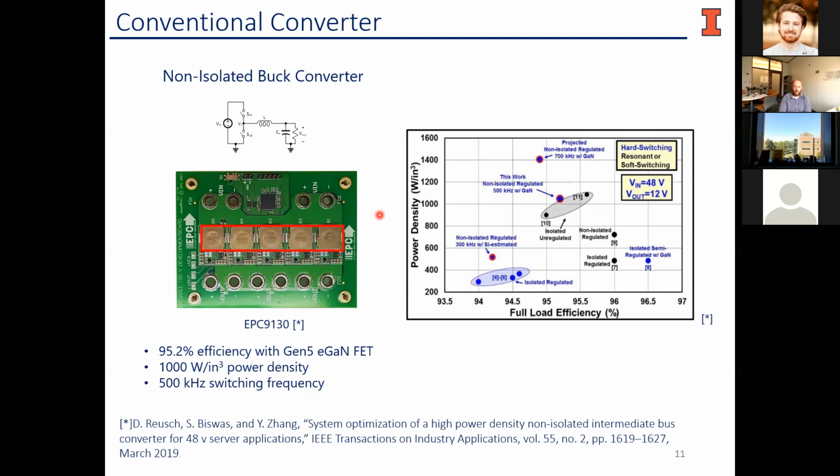We're also seeing that that's basically the efficiency of this power stage. So at a certain point, they draw a box around this and say, here's our power stage. And that's the volume of that. Then we take the power that we're processing, and we get our power divided by volume to get our watts per inch cubed. Another good thing to note is this is a switching frequency of about 500 kilohertz. So they put this out, and they're benchmarking their converter against many other applications.